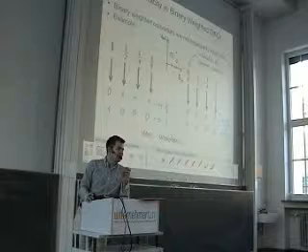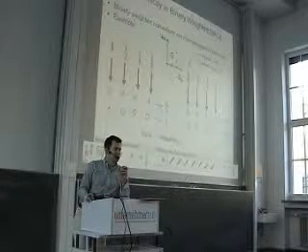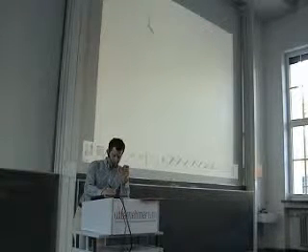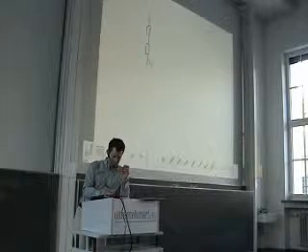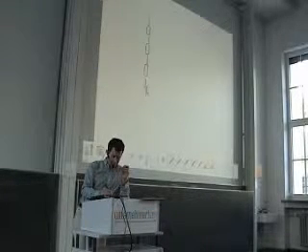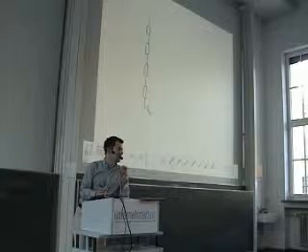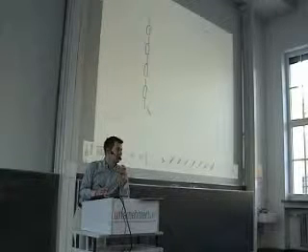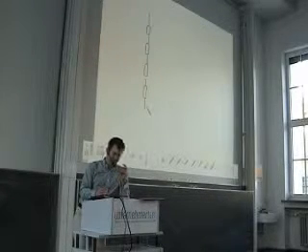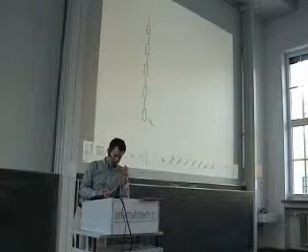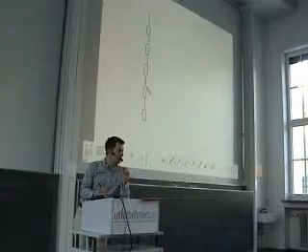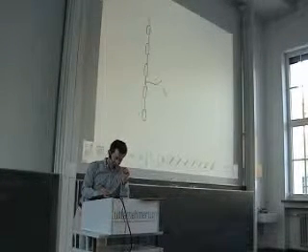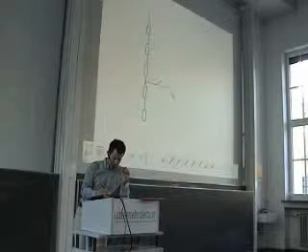Can this happen in a resistor string converter? What do you think? So who thinks non-monotonic behavior can occur in a resistor string converter? Cannot occur? Okay. It's correct. No non-monotonic behavior can occur in a resistor string converter. Why? Well, let's assume we have connected this resistor here to the output.